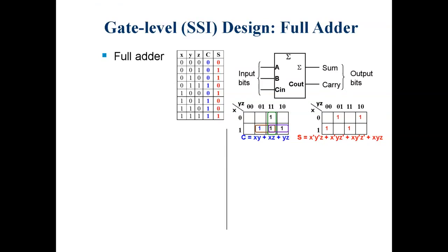Whenever we are adding two n-bit numbers, for the last stage, for a0 we do not need a carry in. So for a0 we can use a half adder, and it may or may not generate a carry. For the other stages, a1, a2, a3, until an minus 1, we need a full adder. Any question? No, sir. Thank you. I hope I answered your question.